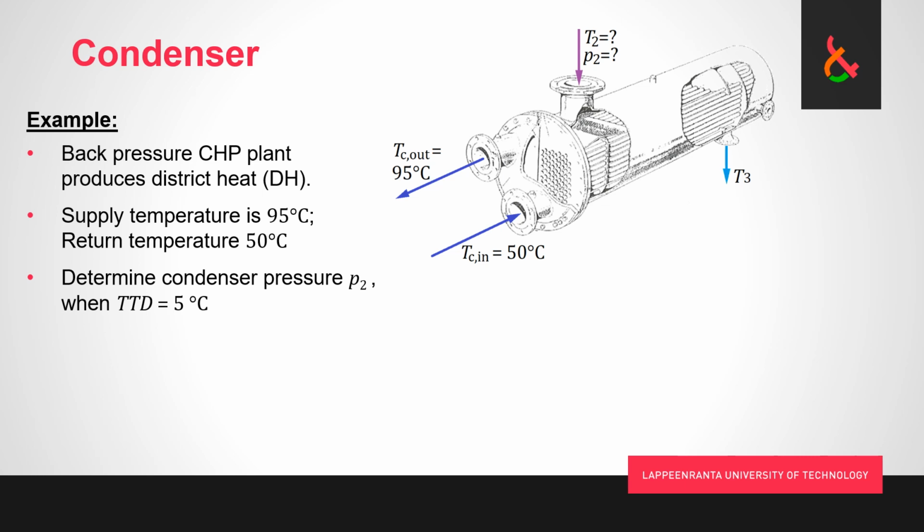So what it means is that we've got the condenser, which for a back pressure plant is a very conventional, ordinary U-tube, shell and tube heat exchanger. Our return water goes in here, gets distributed to all these little tubes. It's a U-tube heat exchanger almost always, so there's just one tube that makes a 180-degree turn at the end, comes out heated, and steam comes to the shell side. It's distributed here, condenses on the surfaces, and liquid drain comes out at temperature 3.